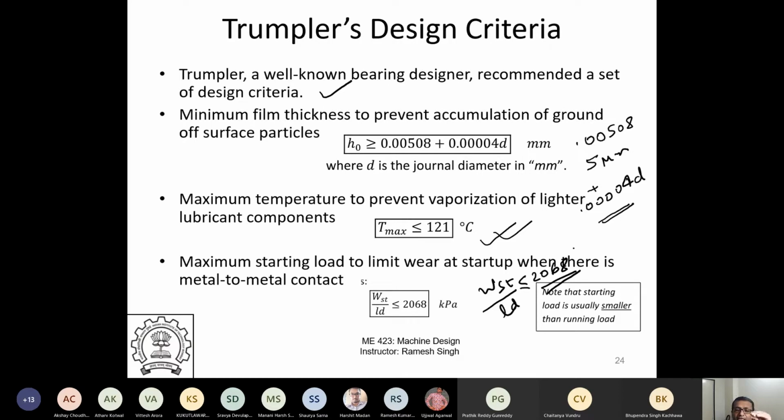This is a special case where fluid pressure building is a function of your speed U. H and P are both a function of your relative velocity, so the pressure creation will happen only after you reach a certain RPM.